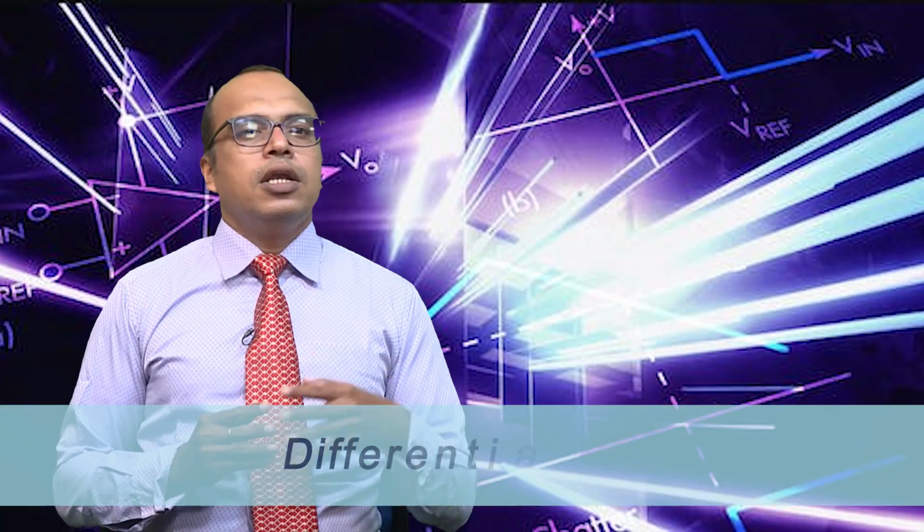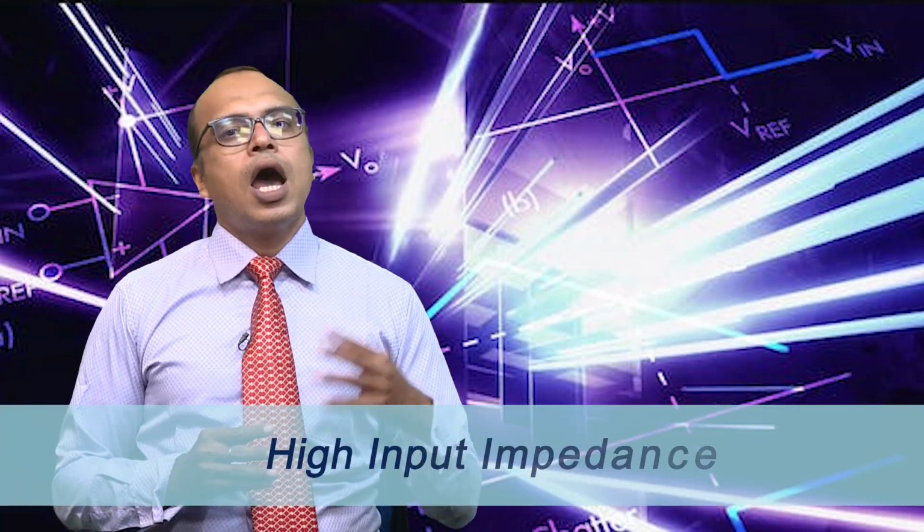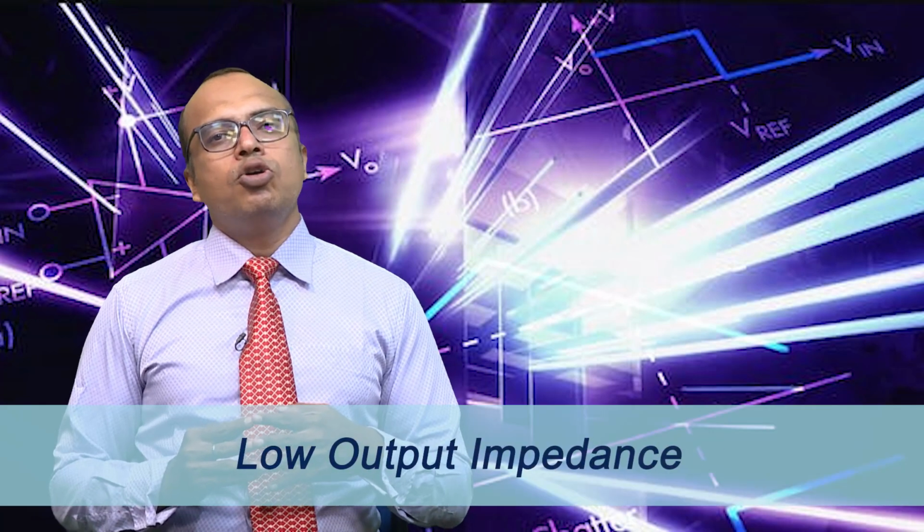Op-amps typically have a very high voltage gain, often exceeding 1 lakh. This means they can significantly increase the magnitude of an input voltage signal. Differential inputs. Op-amps have two input terminals, one inverting, the minus sign, and one non-inverting, the plus sign, allowing them to amplify the voltage difference between these two inputs. High input impedance. Op-amps present very high input impedance, which means they draw minimal current from the input source, making them suitable for interfacing with various sensors and sources without loading them. Low output impedance. Op-amps have low output impedance, allowing them to drive external loads without significant voltage loss.